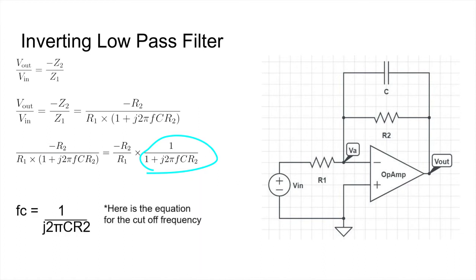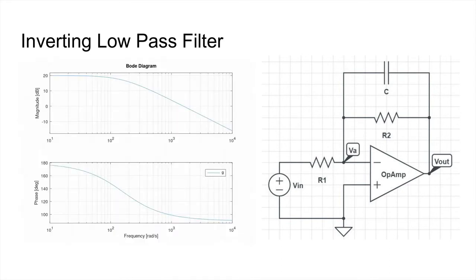Which brings us to talking about where exactly or how exactly this would occur. Well, we always want to talk about where we would find the cutoff frequency. The cutoff frequency occurs where we go negative 3 dB below our original gain, or where we are at half power for this circuit. Once we are at half power, this circuit starts losing a good part of its signal. So that is where our cutoff frequency will be. And for this example, it happens to be right where that red line is.